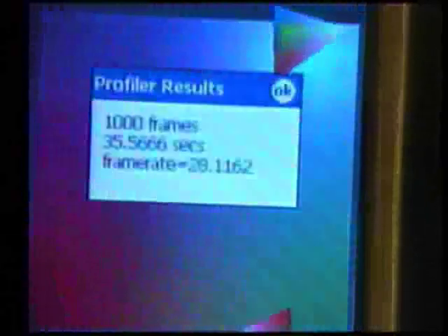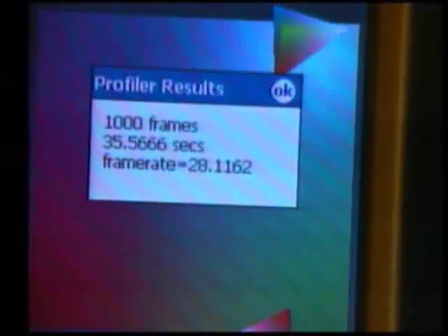Now obviously there's going to be a bit of color distortion from the actual Pocket PC device. What I'm running right now is a Toshiba E750 with a PXA 255 XScale core. This is just a demo, which please come by afterwards and see more clearly up close. Unfortunately, the projector doesn't do it justice. I think it's getting a little confused on the depth that we're giving it and the colors. But this right now is driver technology written by Intel, optimized for the XScale platform. This entire pipeline is producing everything in software optimized for the platform to give you a notion of some of the performance characteristics we're looking at.